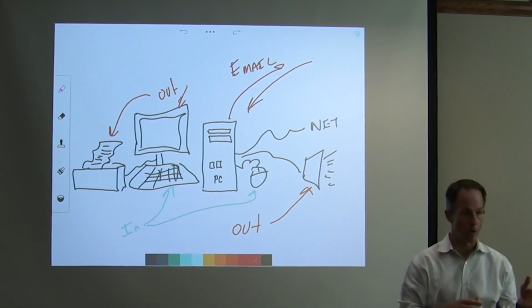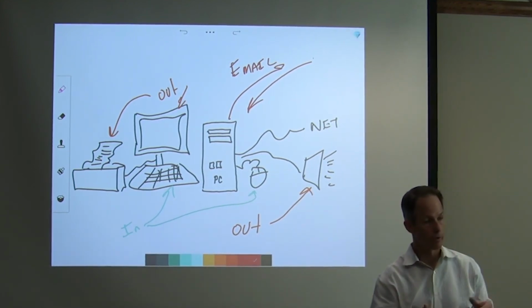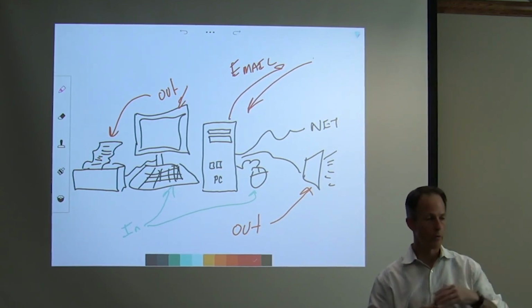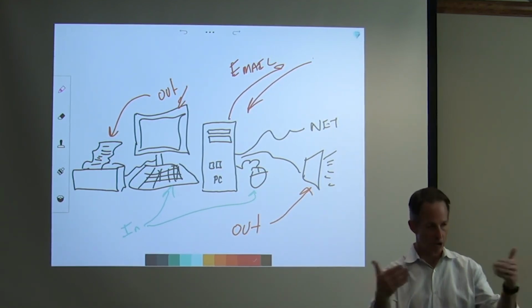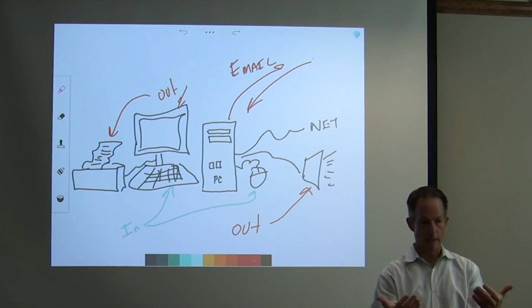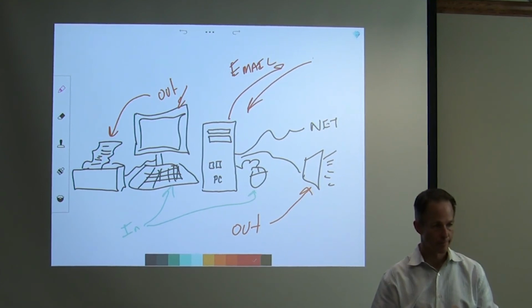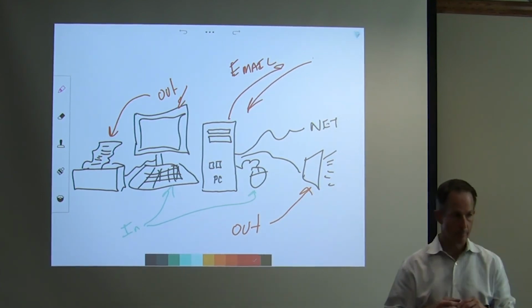Sometimes that doesn't show up until the Jace reboots. Somebody will change a name and it'll continue to work even though it's changed. Then the reboot happens, and the connection tries to be reestablished, and it's like, hey, that doesn't match. The name's different, and then you get the orange. So you may see a value, but it's unreliable because it's not talking.